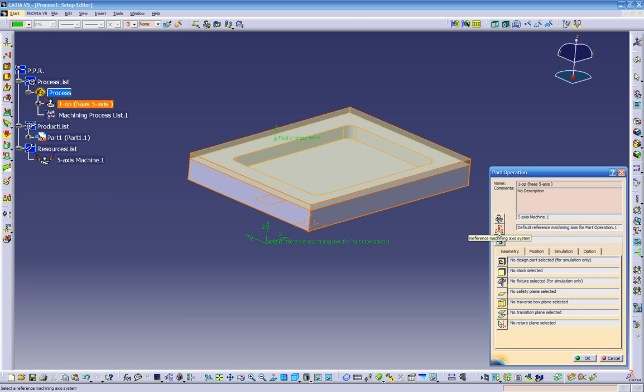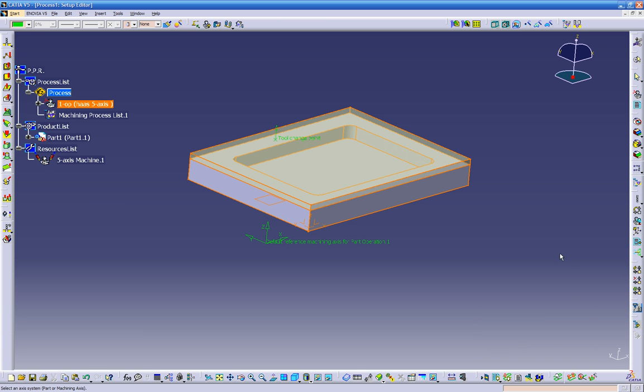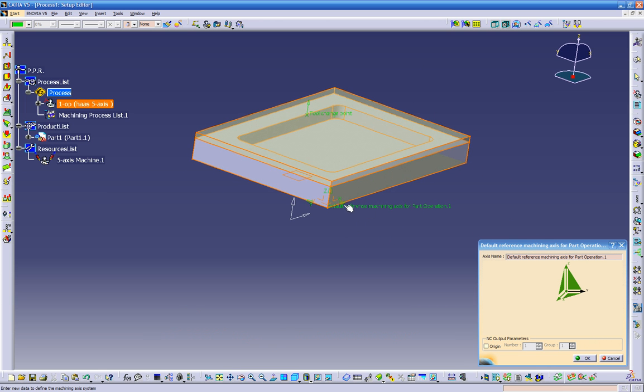Now we have to go next to create our axis. See, our axis right now it's over here, but we have to make sure we specify our new axis. So let's click on the axis and click anywhere on the red area. Okay, and on the bottom left hand corner it says select an axis, and we just click on the new axis that we just created earlier, and automatically it's gonna snap in place.